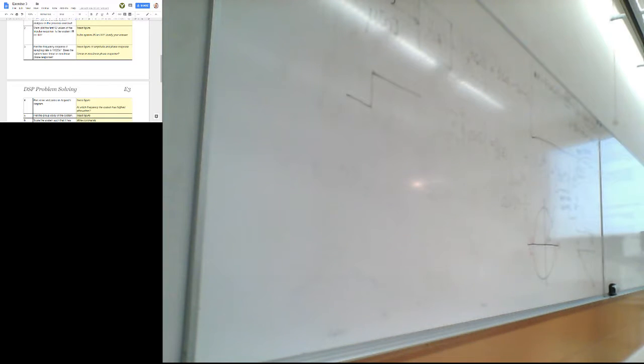For example, a dual tone multiple frequency filter bank. To actually get even the faintest data out of the signal would require quite linear phase response to be able to do it. Okay, so for that reason, the linear phase response is important.